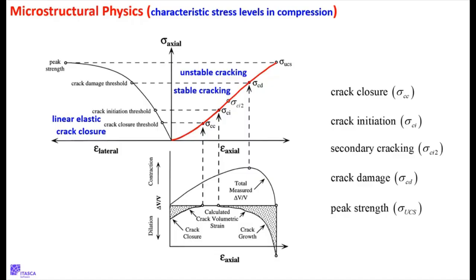And so you just have this structure. It's just like the granular material in that odometer test, after it's all compact in there, there's going to be a while where all it does is just push itself tighter and tighter. There's just surfaces. There's no new surfaces forming. There are all those contacts, and they're just pushing, again, a little tighter. So there's this linear portion. They call this linear elastic right here. Okay.